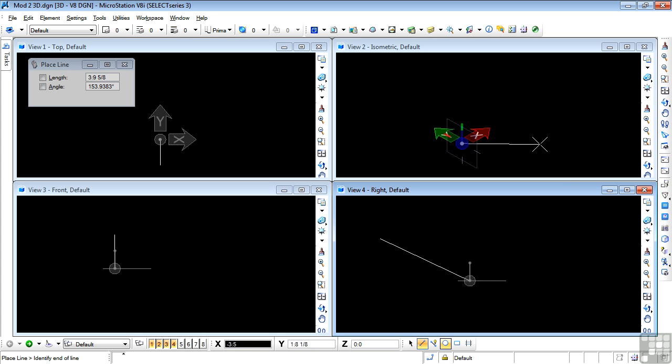I'm going to explain a lot more about AccuDraw in 3D in the next video, but for the moment, just follow my prompts. I need to change the orientation, so I'm going to press F at the keyboard, which is the front view. So the compass rotates into a front view orientation. And now I can start to draw the front face of the step block.